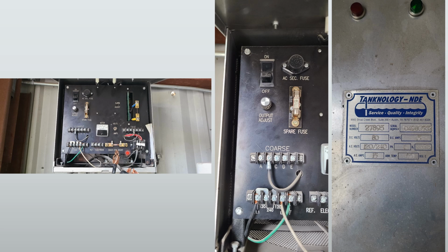This is a technology rectifier. These ones are unique in that the output adjust is there. We also have tap settings here. I've found the trick with these ones. This is a freebie from me. Turn the dial output all the way down to the left before you make any adjustments or turn the unit back on or off. If you do not, you will cause the circuit breaker to trip almost every single time. So turn it all the way down to 0 first, then turn it on or off, then bring it back up to whatever its operating capacity was.